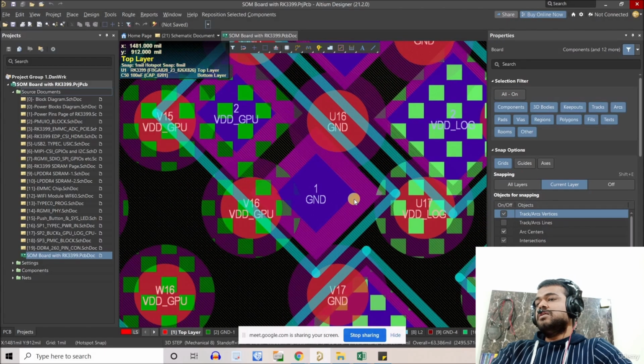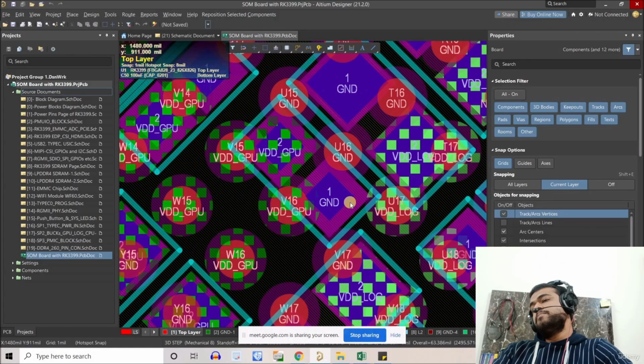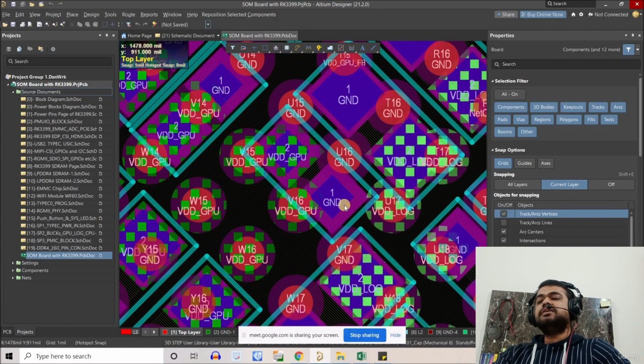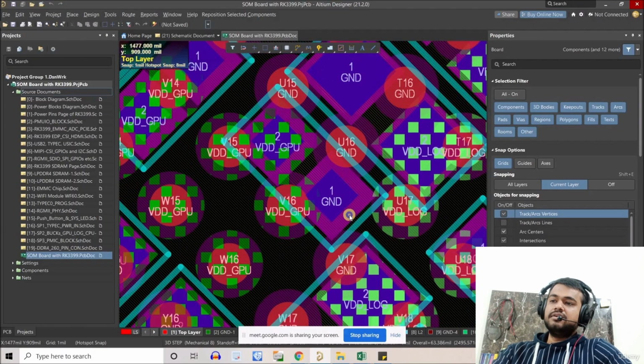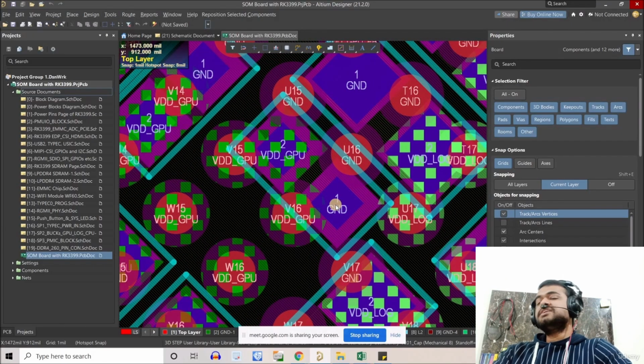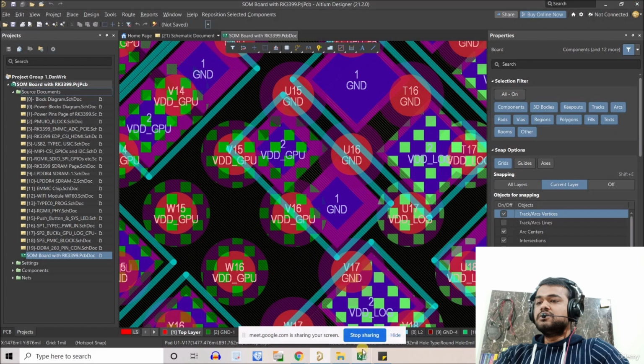During placement or machine soldering, this clearance is again not enough, right? So for that, we're going to use as small a via as possible, and obviously it should be manufacturable, otherwise there's no point in using those.